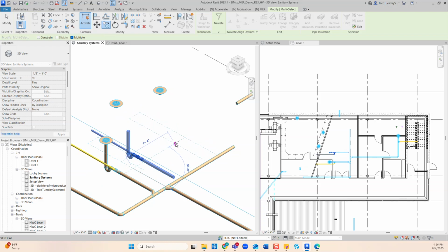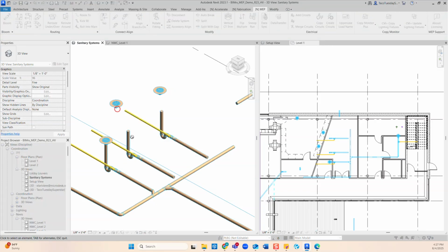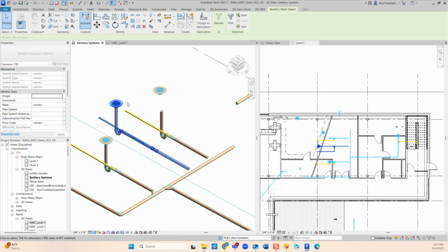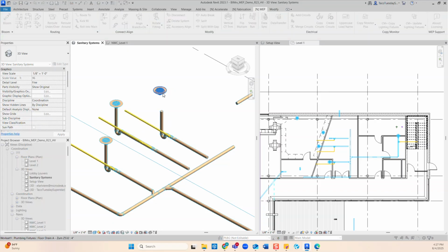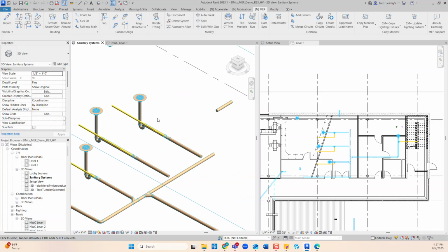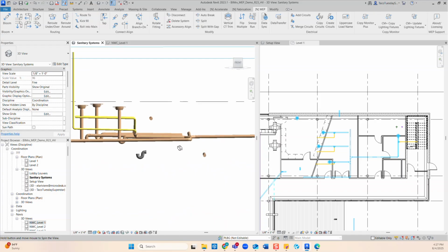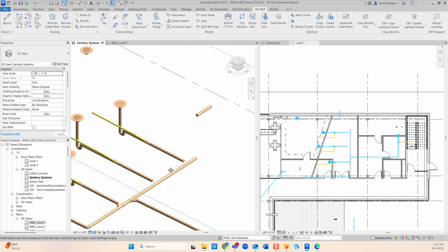So we're just copying what we currently have, right? Let's just go there. There we go. And then we're going to do a little move connect. Yep. And you see if I hover over and tab that they are in fact connected. So another move connect, floor drain. There we go. So now, I'm not aligned with the branch. You can see I'm a little lower. That's fine. So I need to get it aligned.